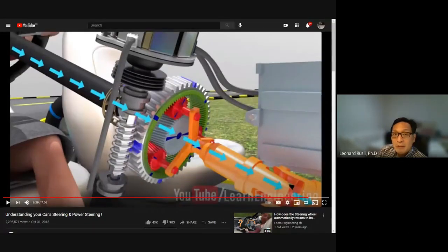This is an electric power steering. Now, in the old days, it's hydraulic power steering. Nowadays, it's getting more and more common to have electric power steering instead of hydraulic, just because of the controls technology that we have now, right? You got the torque sensor. So it only gives you assist according to your effort, right?